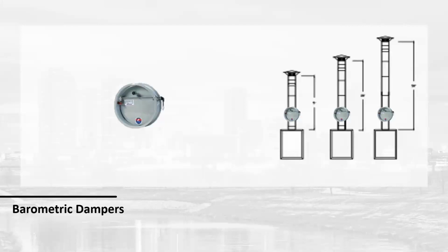So the other thing is we're doing a lot of retrofits. I think 85 to 87% of the HVAC industry is retrofit. It's replacement boilers. It's not new buildings. And so what we're doing a lot is taking out one big 100 horsepower boiler and putting in 3 or 4 modular copper fin or stainless tube condensing boilers. But the owners are wanting to reuse the existing hull. They don't want to poke more holes through the roof. So we put them all into a common vent.